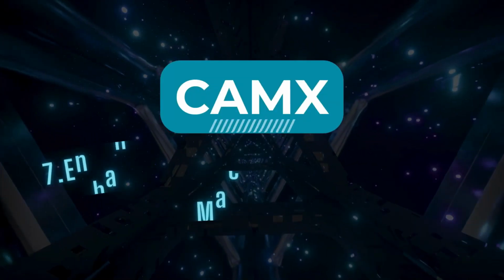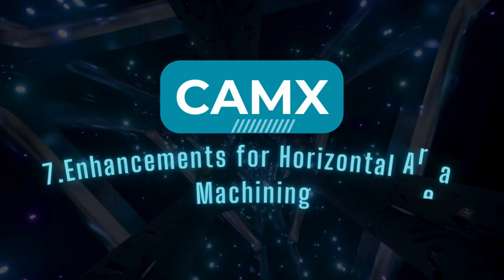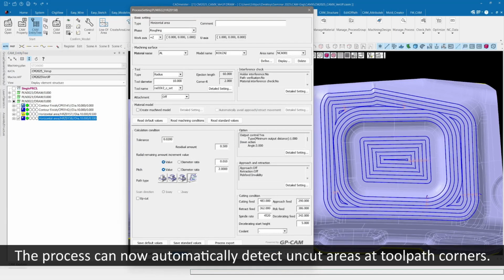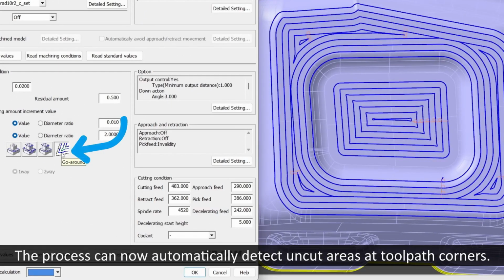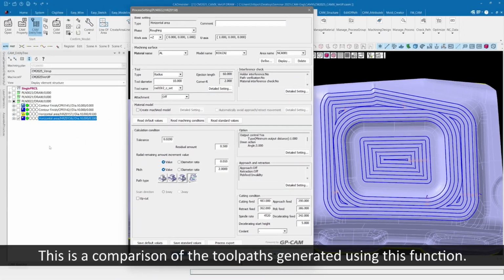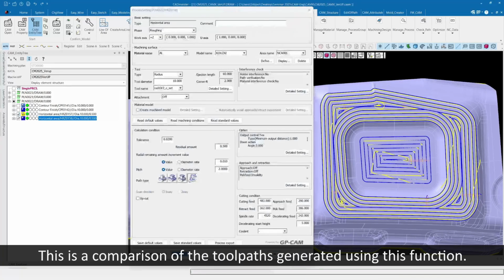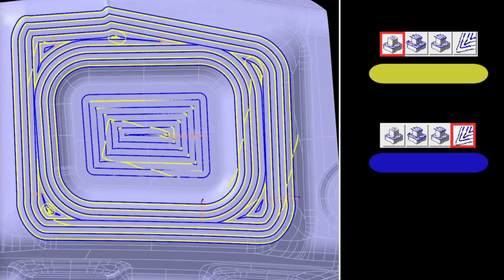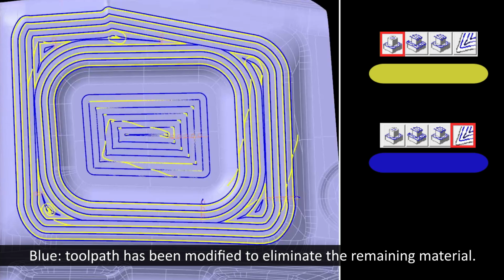The last topic of CAMX, Enhancements for Horizontal Area Machining. With this improvement, the process can now automatically detect uncut areas that remain at the corners of the toolpath. Here is a comparison of the toolpaths generated using this function, so you can clearly see the difference. The blue toolpath shows the modified path, which has been adjusted to eliminate the remaining material at the corners.